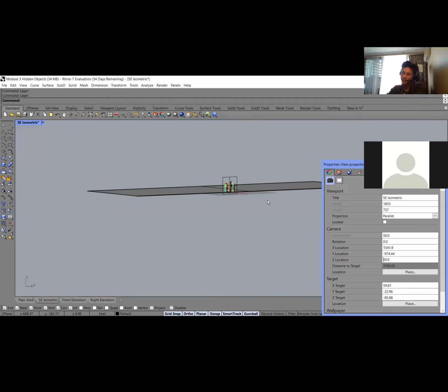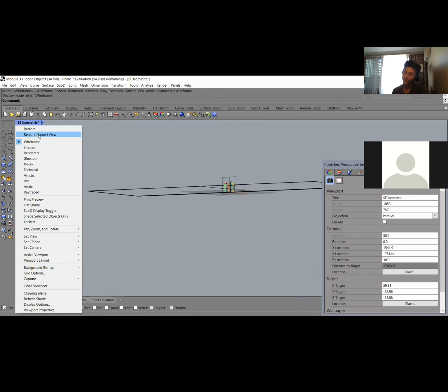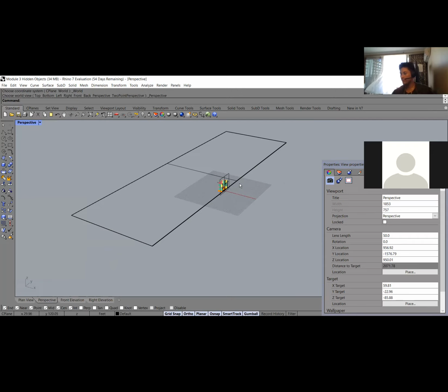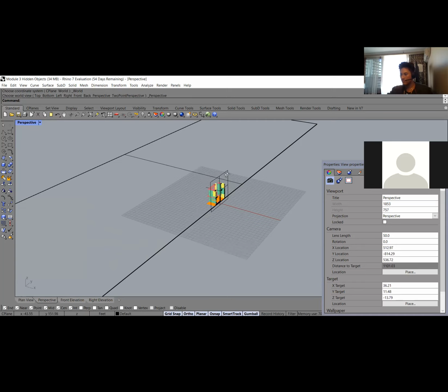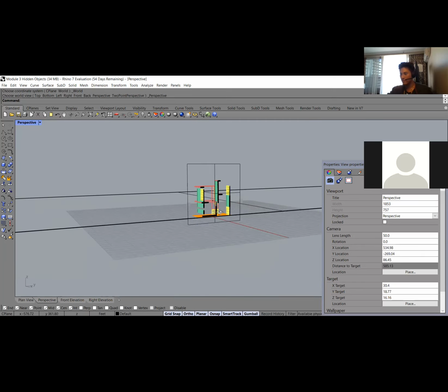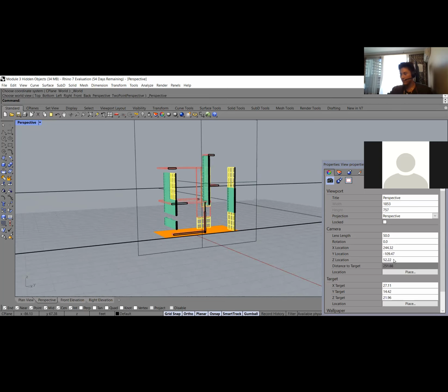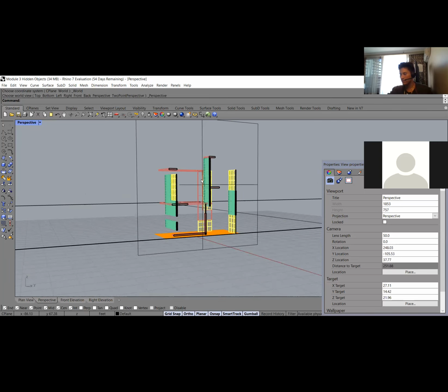Oh, you know what? You have to set your view to a perspective view. You're still on the parallel view, your isometric view. Yeah, so click that tab and set it to perspective. So go down to set view. Down. Yep. Perspective. So now do your 30-30, or do the view like how it was. Rotate it. Okay, now zoom in and then do your 30-30 on your Z location and Z target.